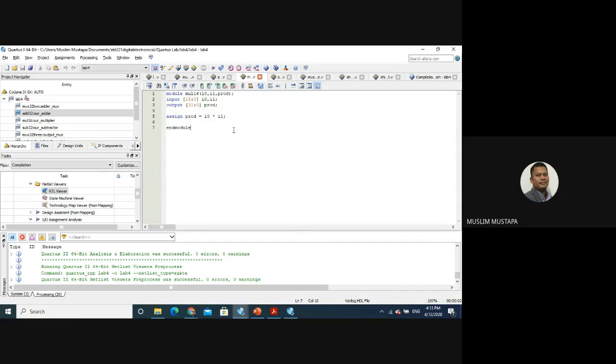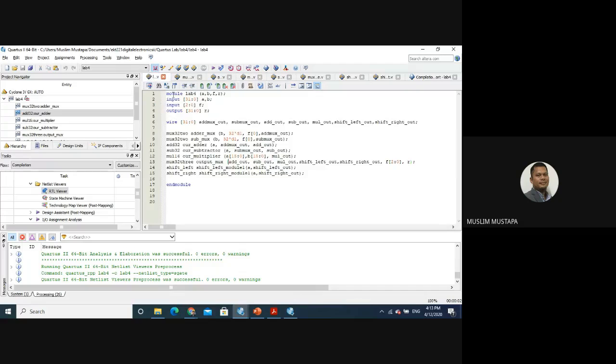Let's say, for example, we have a problem in the multiplication result. You can create one new project with just one module to check whether this module functions as you want or not. If you find out, okay, no problem with the module, when I simulate it alone I get whatever result of multiplication that it gives, that means you have a problem in your connection. So just check through your connection. So this is how you debug. You break it into small pieces and try to find where the problem is.